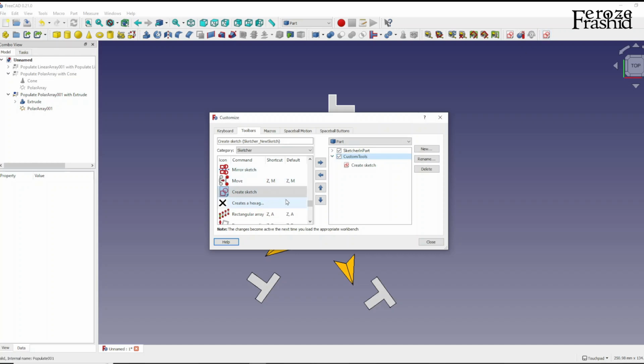And if you wanted to have other tools, say, what other tools have I been using? Say Part Design. I want to bring in subshape binder. I use that a lot in the Part workbench. I actually want to place it in there in my original toolbar. So I have create sketch, slice apart, create a clone.